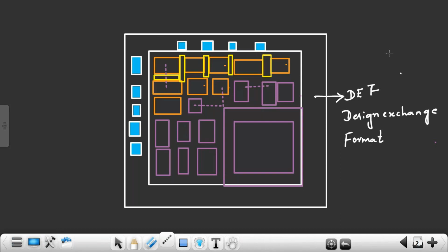For example, for total standard cells and macros, if I need a 1000 micrometer square area, I cannot create my core area only for 1000 micrometer square. I should consider some 20% extra, 25% extra, 30% extra. In block level design, it depends upon the chip top how much extra area is given.